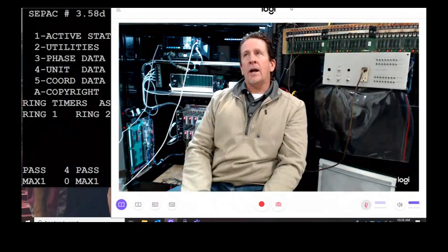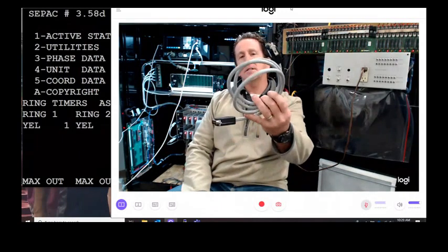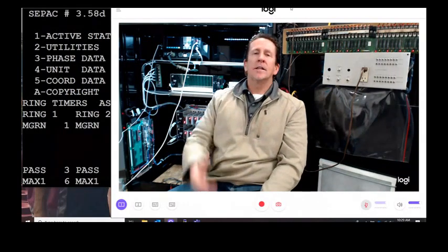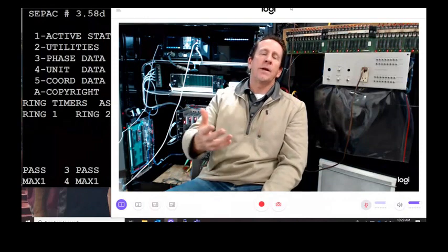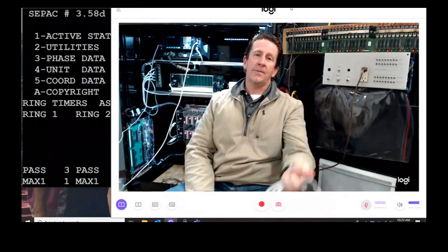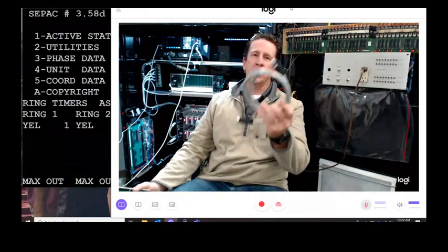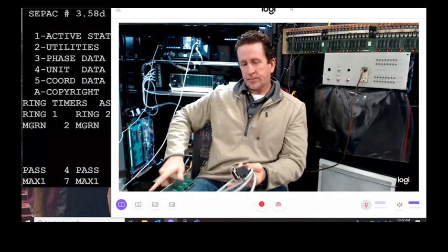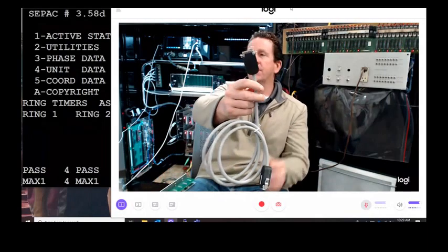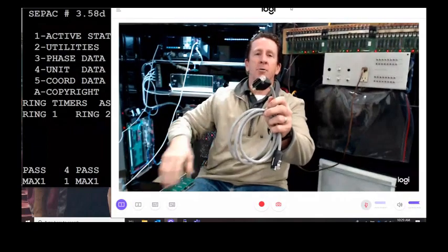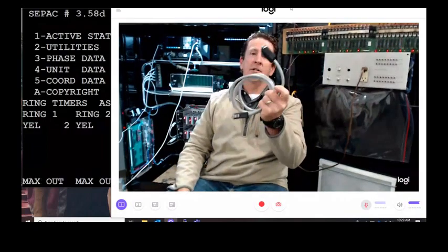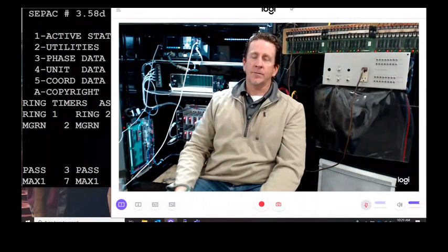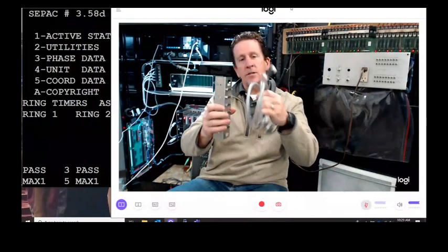So again, I don't think the BIUs are the problem. I think it's the different kinds of SDLC cables that manufacturers use and how they pin out the devices that breaks down the data communication, which may lead you to say, you know, manufacturer A's BIU doesn't work in C's cabinet. I think it's more the cabling. We use the hub assembly. Other manufacturers just have this as a free wired end, and they just do terminations onto a terminal block. So that just adds a lot more failure points. Now you're more susceptible to corrosion. That can all break down the data. So that's my take on BIUs and SDLC.